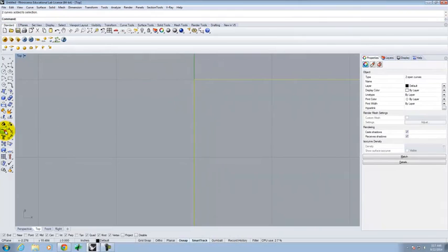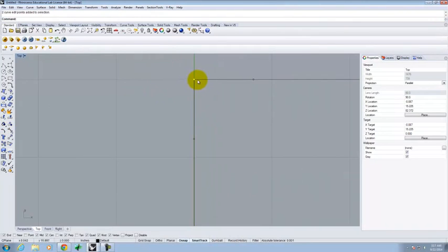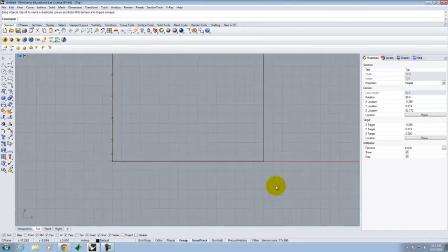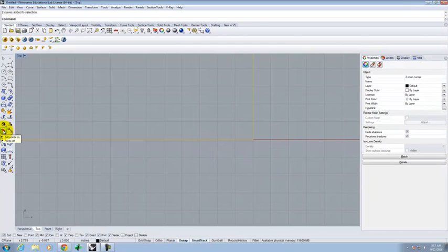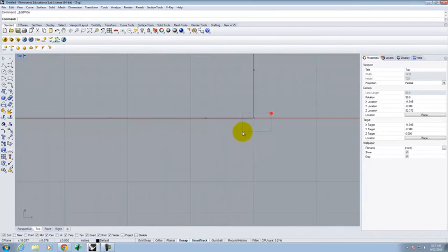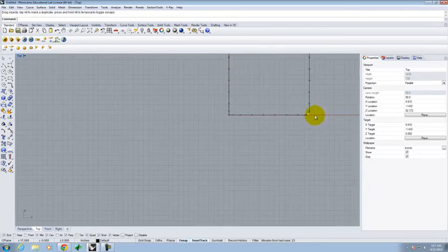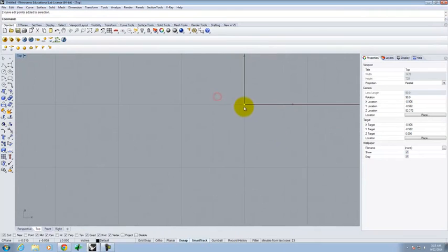I do want these points to stay connected. So when I have my edit points on, I want to make sure that I select both points, and then I can drag those points as well. If you feel more comfortable using the gumball tool, you can do that for this as well. And make sure these points are on. Select both of those, and I'll drag these down as well, like that. And we'll do the last ones here.